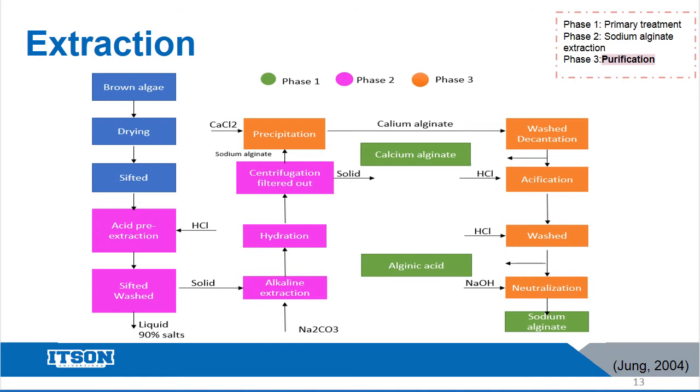Phase 2. Extraction of sodium alginate begins by reaction with hydrochloric acid. This allows the exchange of cations present, transforming the alginates of the solid matrix into insoluble alginic acid, which allows a more efficient recovery of them. This treatment is carried out with the solution for 2 hours.